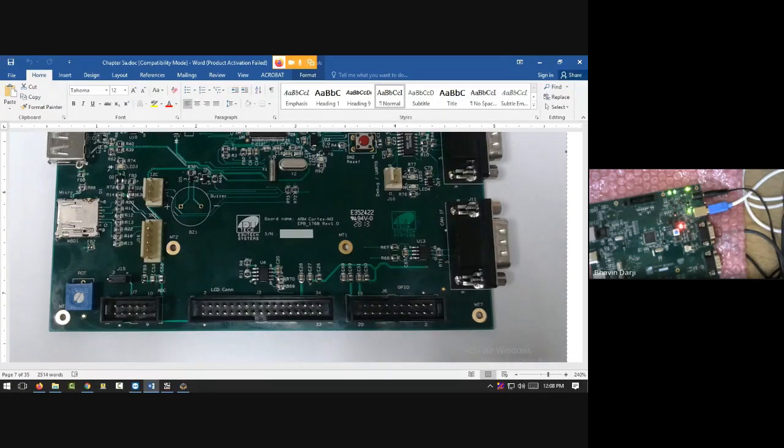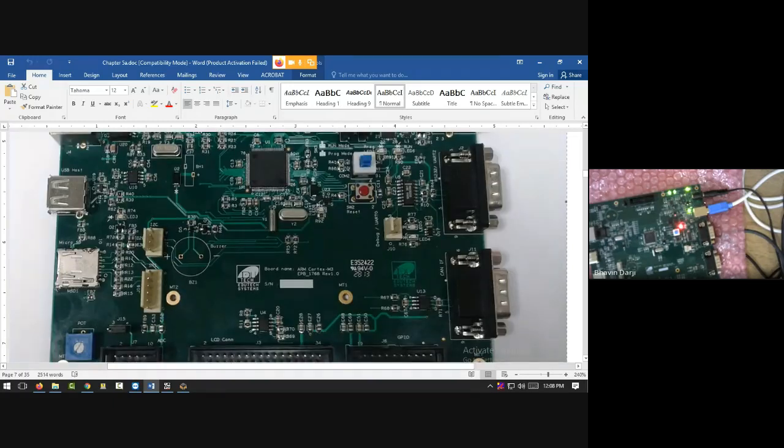So this is the ADC feature available on this kit, and there are sensors like soil moisture sensor which sends data in ADC format. There is a water sensor which also sends data in ADC format. There are sensors for signal detection, like a voice or mic sensor. If there is a small sound, it will generate some voltage. That voltage will be converted into digital format, and the data will be displayed on our web page, or I can say the IoT system. So ADC is also an important part in IoT.